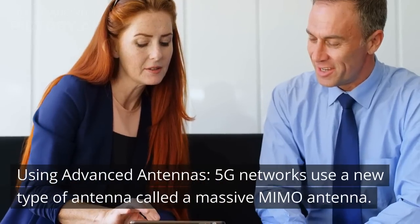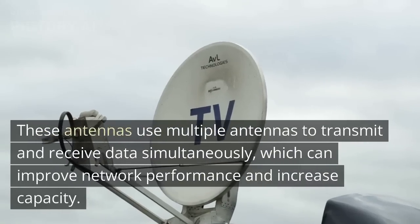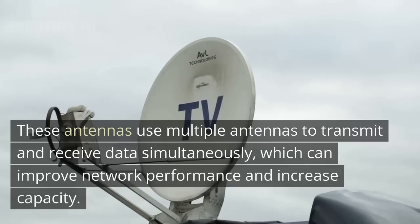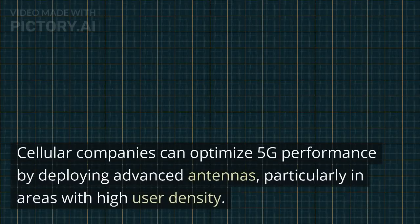Using advanced antennas. 5G networks use a new type of antenna called a massive MIMO antenna. These antennas use multiple antennas to transmit and receive data simultaneously, which can improve network performance and increase capacity. Cellular companies can optimize 5G performance by deploying advanced antennas, particularly in areas with high user density.